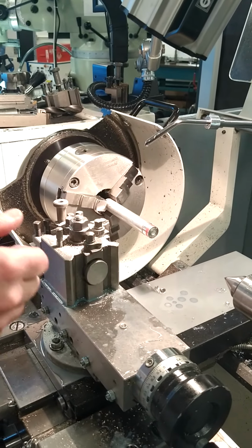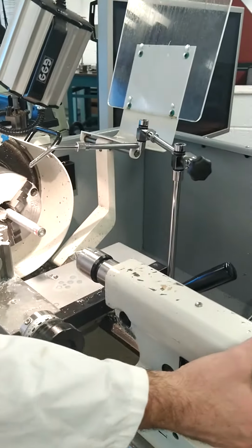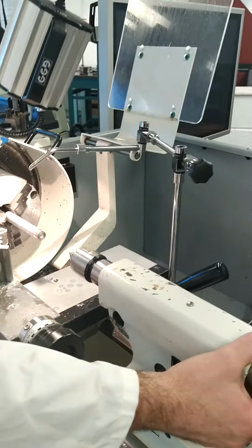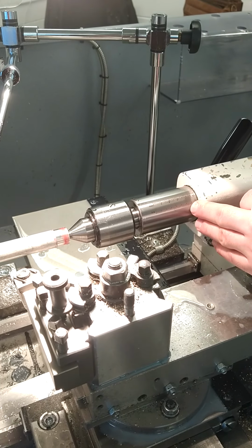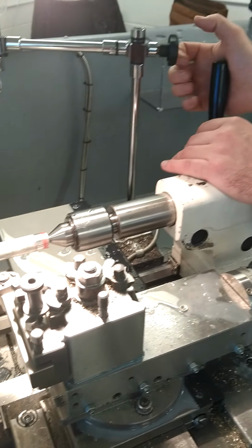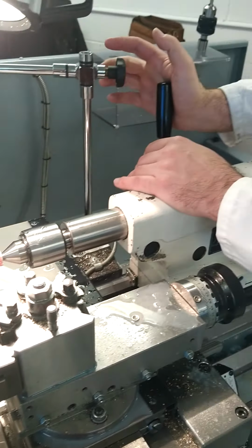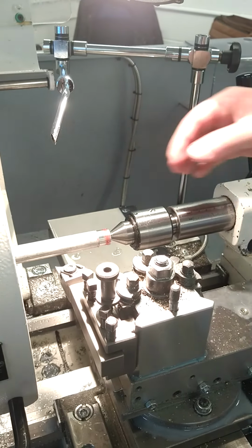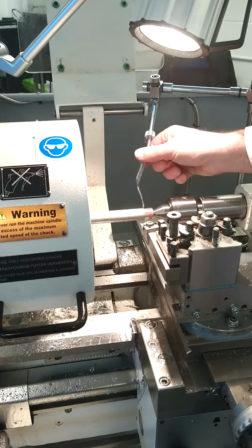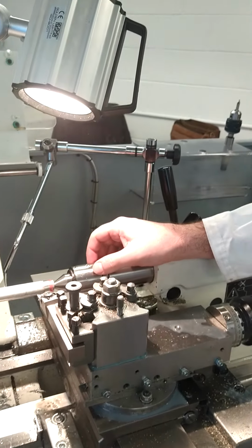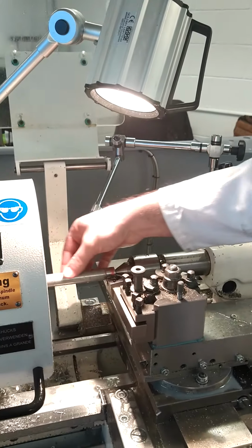So by supporting the work, what we can do is push in the tailstock and get set up here by adjusting it out, again 60 millimeters of a distance to ensure everything moves freely. So you apply on your lock in the tailstock, and now what you want to happen here at the end of the video is we can now turn down that diameter of the bar the full length.